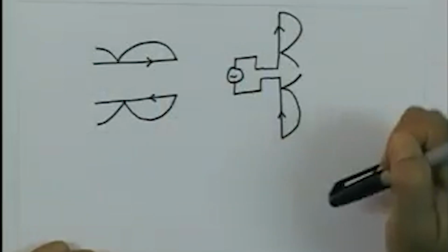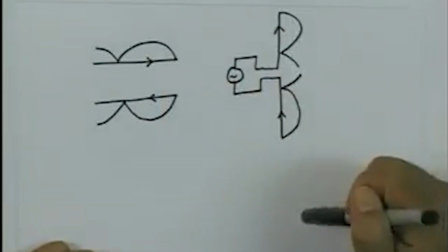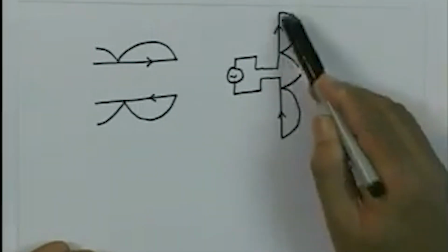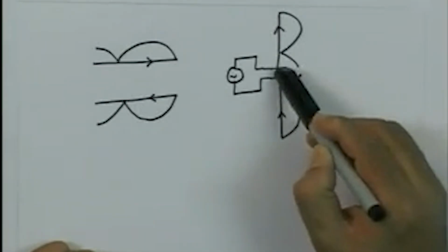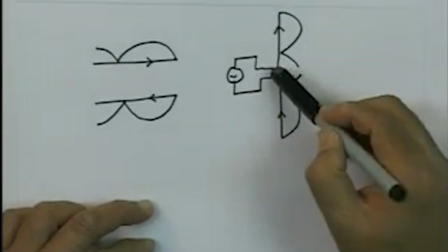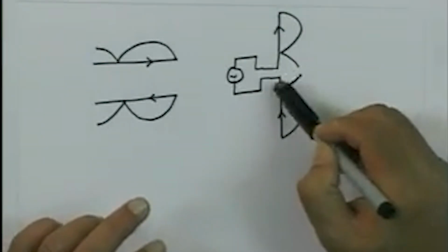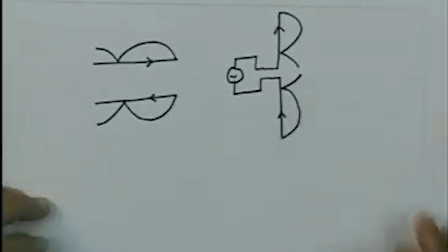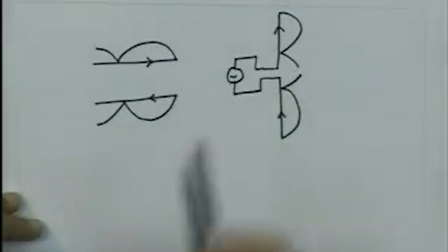That means the input current which flows on the antenna is not in the control of the designer. What he can do is simply design the length of this antenna, since the current has to go to 0 at the end of the antenna, and this function is a sinusoidal function. Depending upon the length, it might have a certain value of the current at the input terminal of the antenna. So, input terminal current is decided by the length of the antenna. There is no independent control of the current for a given voltage excitation.